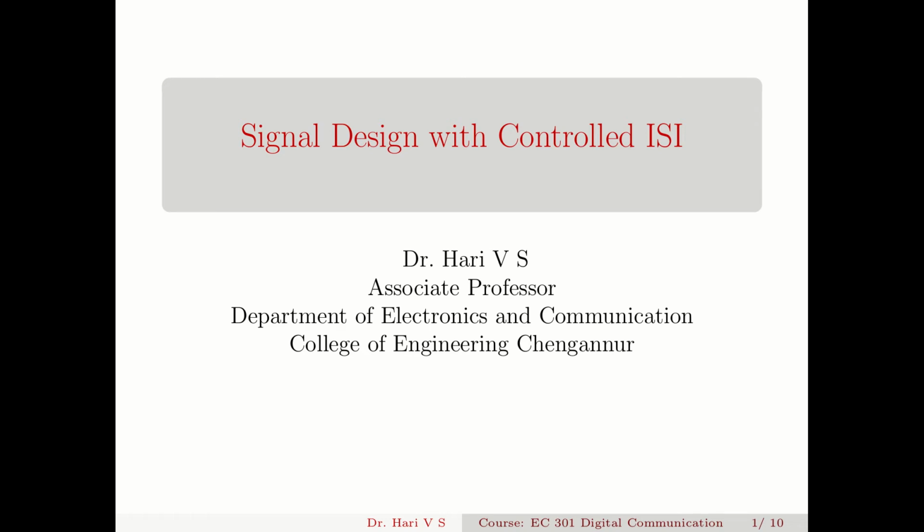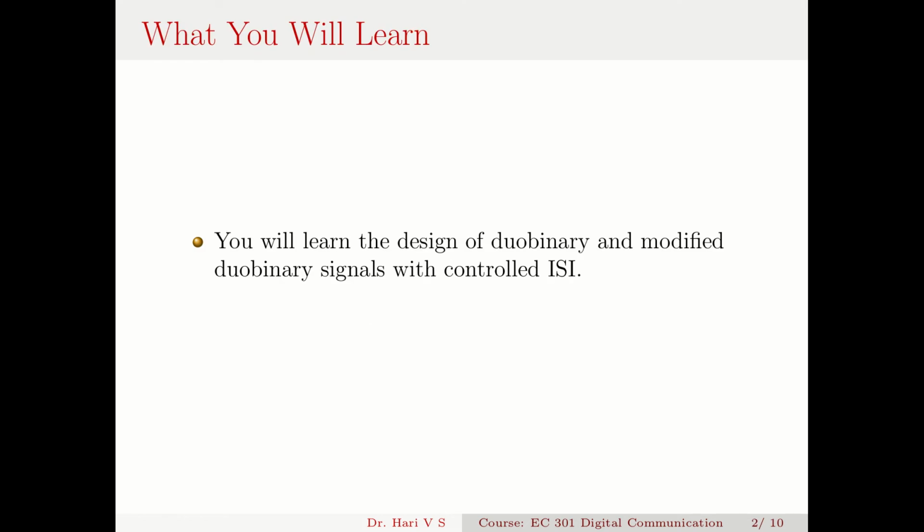The speech is organized into the learning outcomes. You will learn the design of duobinary and modified duobinary signals with a controlled ISI. There is a limited amount of ISI. That's a controlled ISI. You allow some ISI so that you can have a convenient signal design.